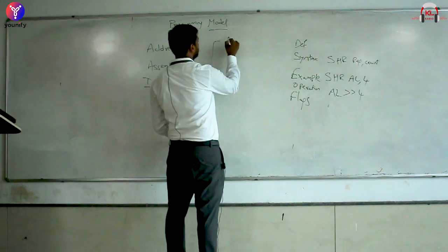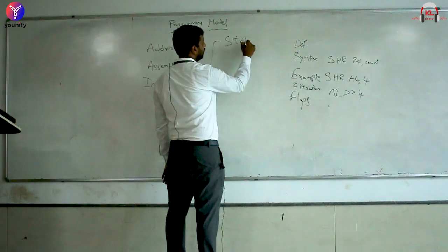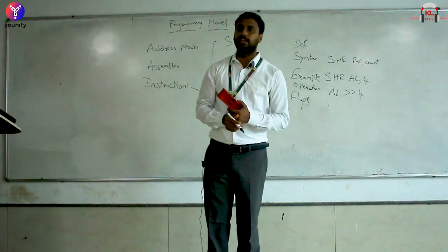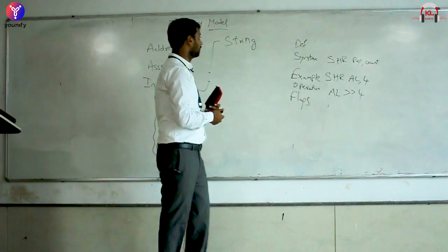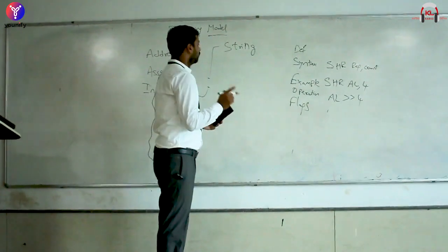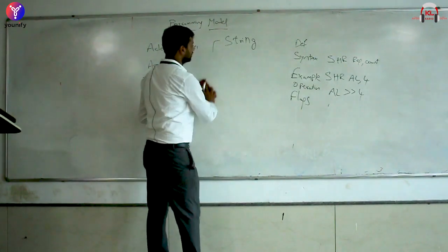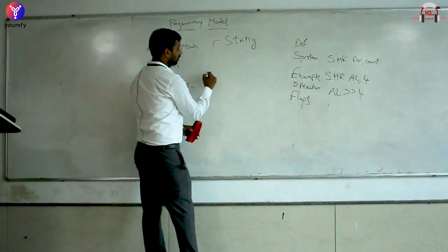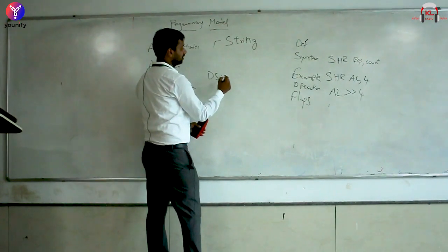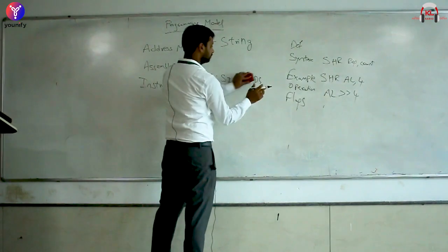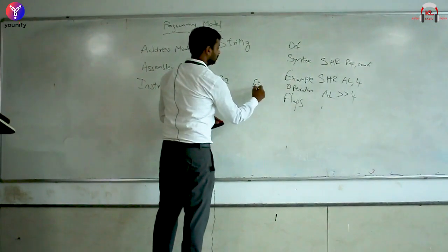And one set of instructions that are to be noted are the string instructions. Similar to the data transfer or compare, we have a bunch of string instructions. One important way to understand all the string instructions would be that the source of the string instructions is DS:SI, and the destination is the extra segment: ES:DI.